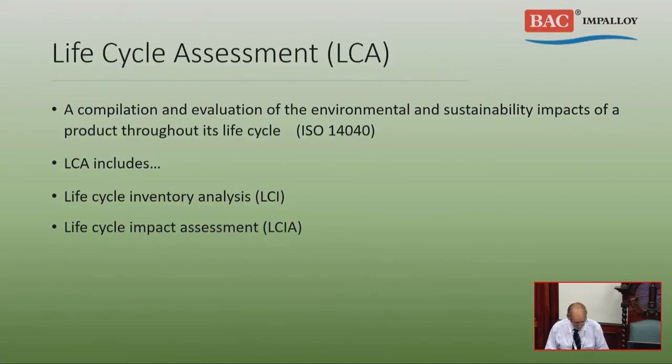Right, so what we have to look at in CP terms is what the impacts are. Well, CP, for those of you who don't know, relies on the supply of an electric current. You make the structure the cathode of an electrolytic cell, with the corresponding anode, which can be either galvanic, naturally producing the current, or impressed by an external power source.